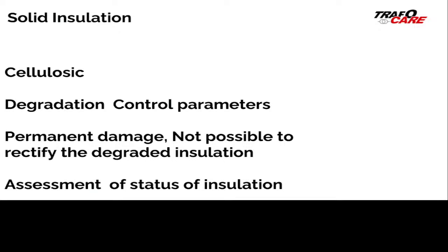Now, the next important aspect is solid insulation. All these have a major impact, and solid insulation will have the major system damage. Whatever damage occurs to solid insulation is permanent damage, and if it degrades to a level where we cannot sustain functional continuity, this component will affect it in a major way, and we have to give it higher weightage. So it is better to see how much moisture has entered the insulation. Retained moisture monitoring is very, very important.